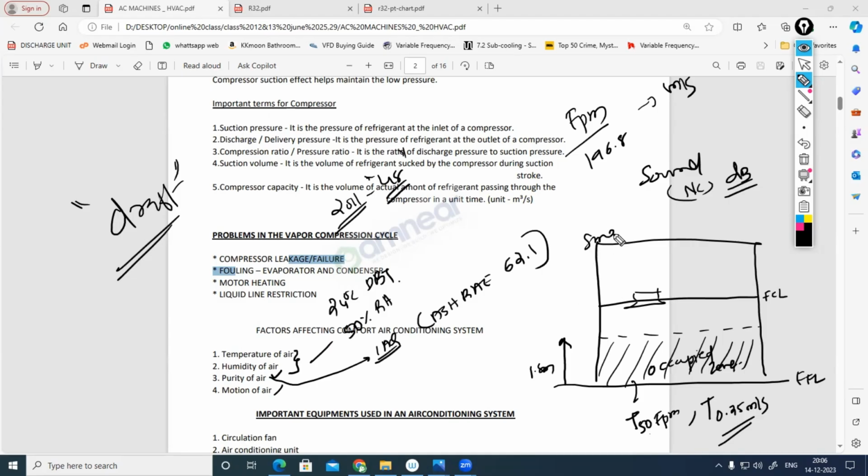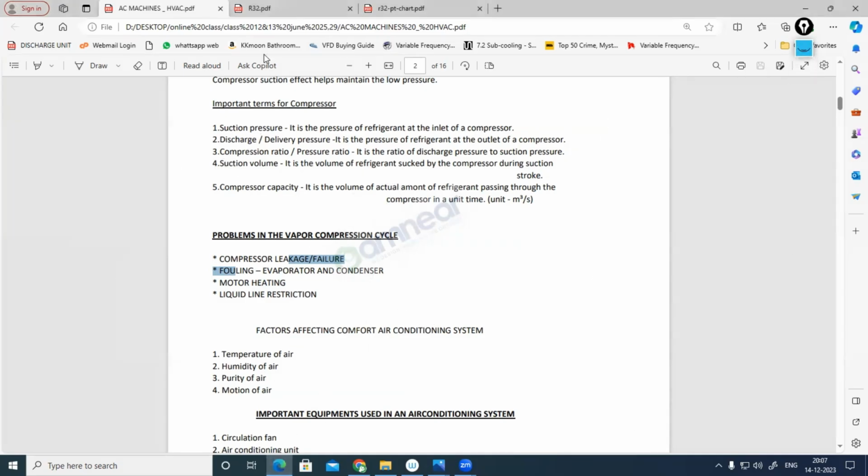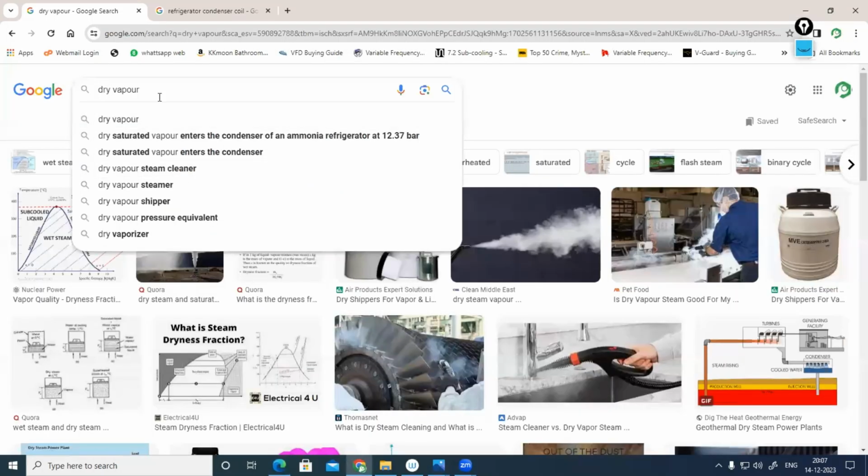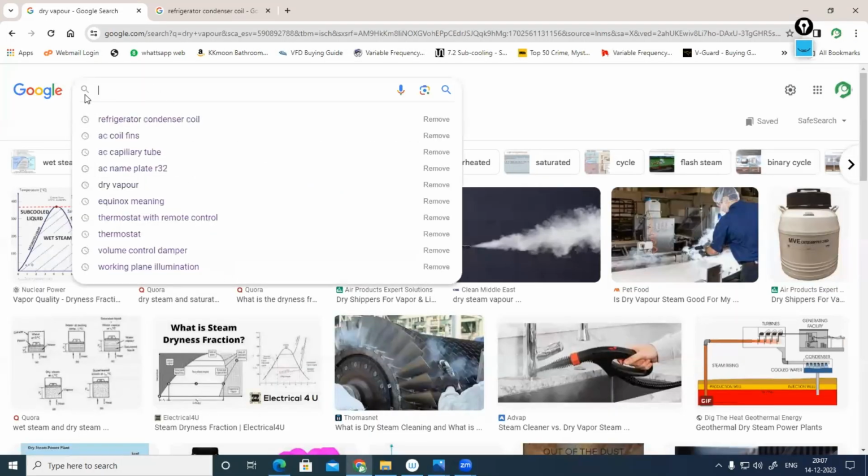Odor, smell, is also important. If the air is not perfectly purified, then the smell also has to be removed. To remove the smell, on the filter side, if you are getting bad air, we provide activated carbon air filters. Normally that is an integral part of a kitchen exhaust system.